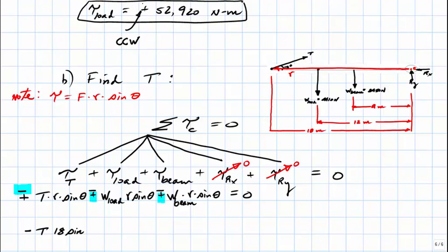We can extend the moment arm as well as the tension and create an X. And of course, we noted earlier that any angle within this X could be introduced into the torque equation. Now, we know one of the angles inside of this letter X, and that angle, of course, is the 15-degree angle, and so that is the angle that we will incorporate.